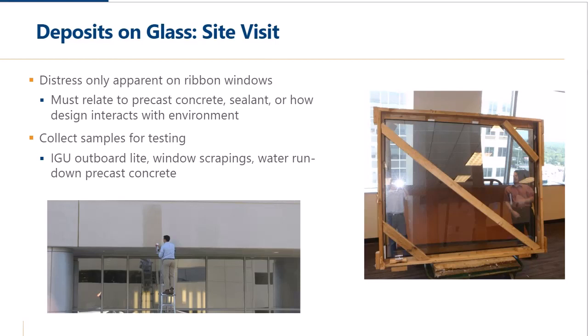And one of the other things we did based on the site observations is, it looked like those deposits were sort of drip-like features. So we wanted to understand what would happen with interaction with the glass and rainwater coming down the concrete. It was a dry day, so you see a colleague there taking some purified water in a spray bottle, wetting down that concrete until it dripped down, and then collecting it into a container so we can look at water that's run down the concrete.